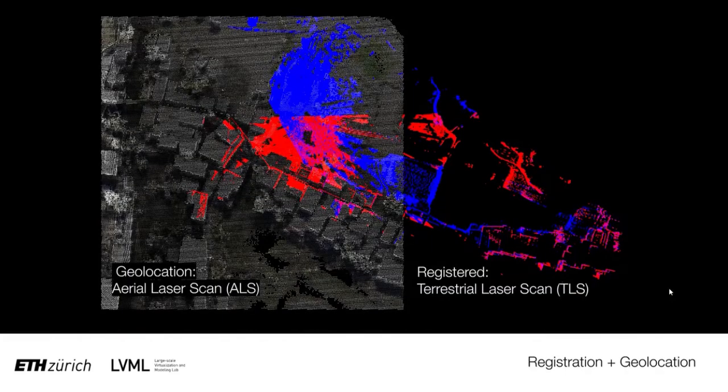Point cloud models that are distributed usually contain georeference. This is also the case on the dataset we'll be using today. So they are already geolocated in space and usually refer to a certain projection grid. When we scan with a terrestrial laser scanner, we are not working in a georeference. What we can do, though, is to then combine the two datasets.